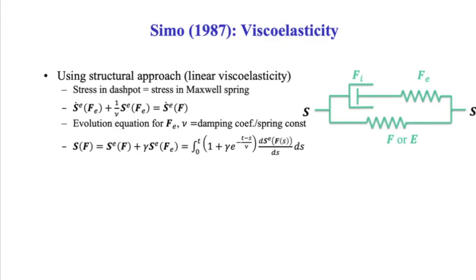However, because we wanted to start implementing damage in viscoelasticity, we needed to do that in FEBio. So I'm going to take you through the process, and you need to understand what we're doing here. Basically, strain energy can only be formed in the springs. So if you know that the spring is deforming, 1/2 of kx squared would be the strain energy in a spring that deforms by length x. And so the same here.